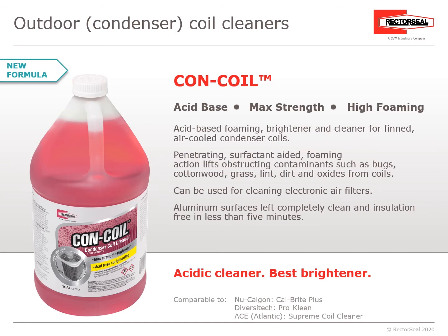It's an acid base, max strength, high foaming condenser coil cleaner. It's an acid base foaming brightener and cleaner for finned air-cooled condenser coils. Penetrating, surfactant-aided foaming action lifts obstructing contaminants such as bugs, cottonwood, grass, lint, dirt, and oxides from coils. It can be used for cleaning electronic air filters. The aluminum surfaces are left completely clean and insulation-free in less than 5 minutes.